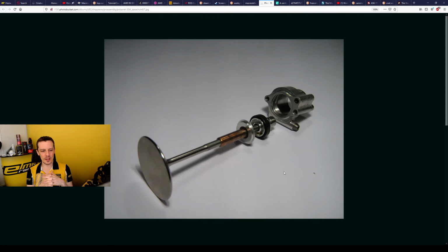And I'm assuming the stiffness of titanium goes down when the temperature increases. I could probably try to dig up some curves somewhere, but we're not going to get into material tech too much. So titanium will typically be used because the density of titanium is lower than iron-based alloys or nickel-based alloys like Inconel. Then you can have the same volume of a valve but lower weight. So running larger valves, higher RPM, that means you have more benefit of titanium. So you'll typically see intake valves on motorcycle engines and stuff like this will be titanium.